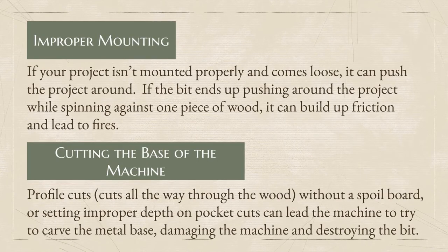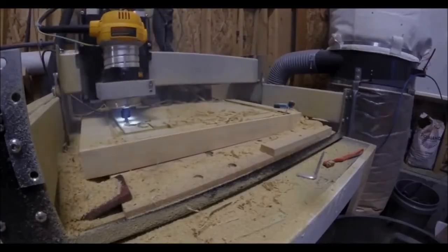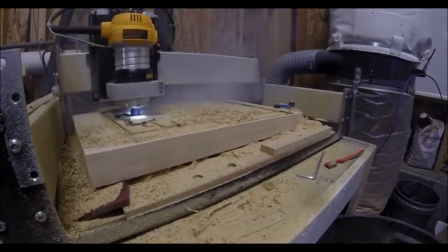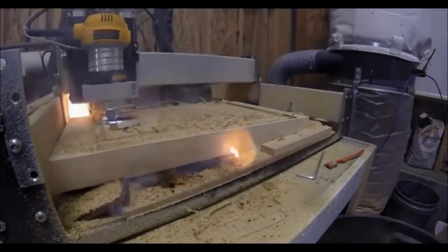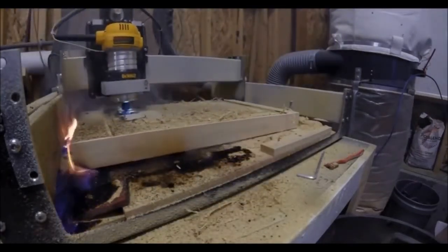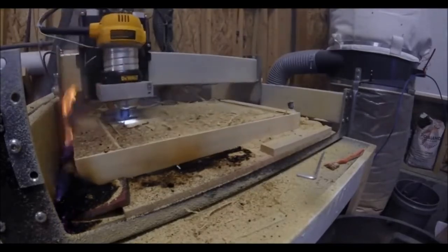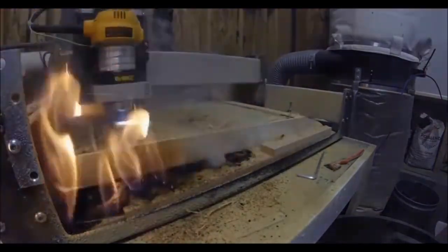It is very important that the workpiece be secured to the CNC table. Without doing this, it is possible for the workpiece to move around, which could cause injury. Also, jamming can occur due to improper securing methods. Resulting heat from jams can ruin the finished product and also has the potential to start a fire.